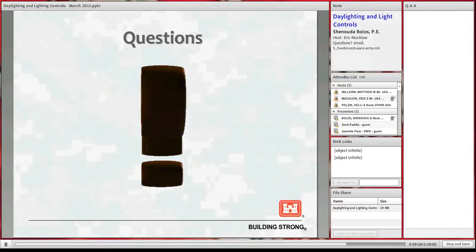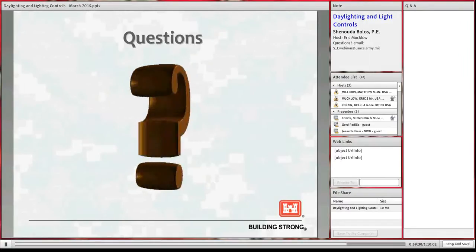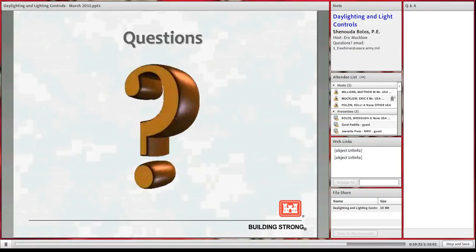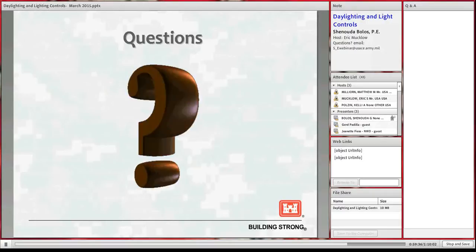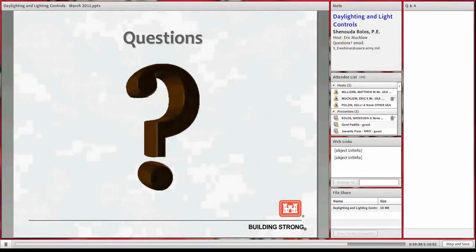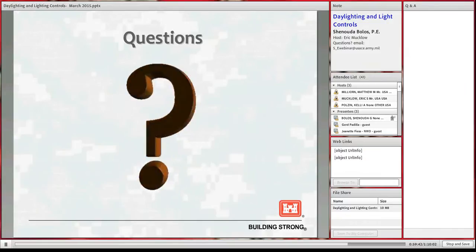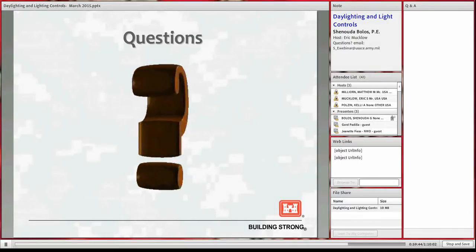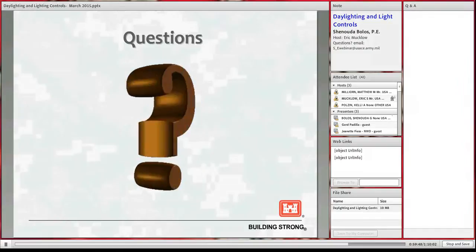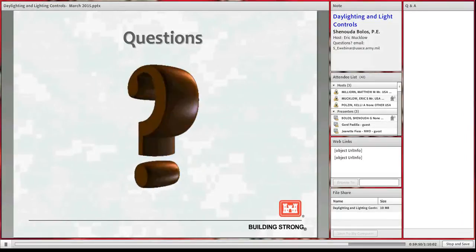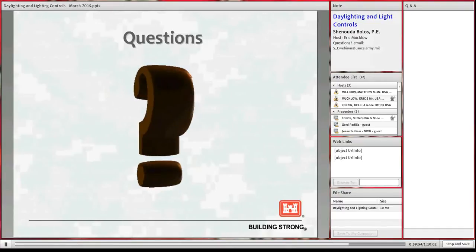Here is a decision between, again, the architect and the electrical engineer, because the architect defines what the room type is. If it's an occupant room, then it becomes a requirement for LEED that the room is occupied, and you have to meet all requirements for daylighting and lighting control. If the architect defines that as occupant space, there is a different definition of how you go, like whether a mechanical room is an occupant area or not.